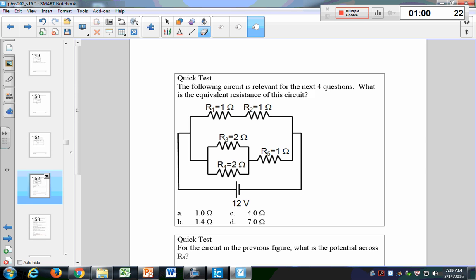So what you're asking yourself is, if I change the resistance down here, how am I changing it? Well, if I remove this resistor, I increase the resistance of this branch. Because remember, when you add resistors in parallel, the equivalent resistance goes down. I'm giving those electrons more paths to take.